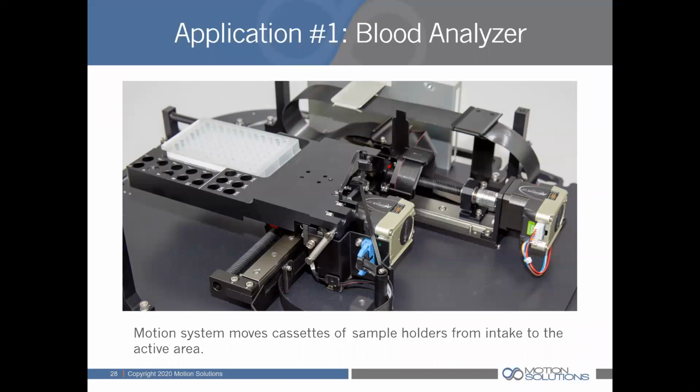So the requirements for this motion system were that the sample tray position the cell under the pipetter within a certain tolerance. You might think you have something like a 2 millimeter hole in that well tray, and a 1 millimeter pipetter coming down, and that gives you about 0.5 millimeter on each side. So you want to be well within that as far as your accuracy.